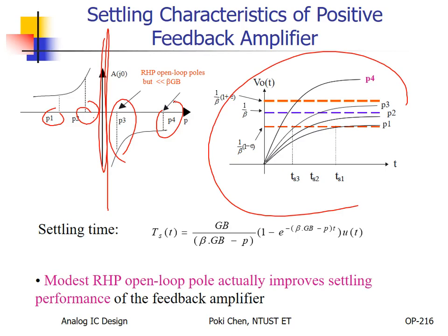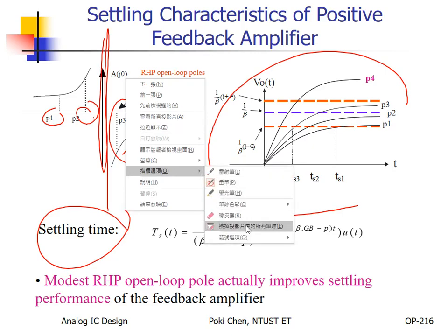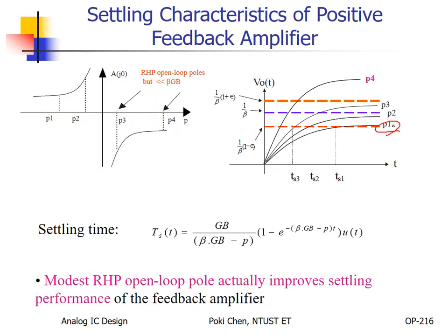And we would like to simulate the settling time. Allow me to show you. In the past, you have only P1. You only design P1 and P2 for your op-amp, right? The two negative poles to stabilize your op-amp mean the longer settling time. Okay? If you are brave, push the poles close to the boundary. You can see, you can speed up the settling time, right? P1 here, P2 there, right? The settling time is reduced.